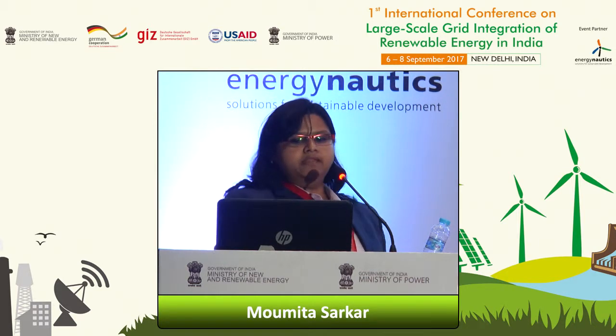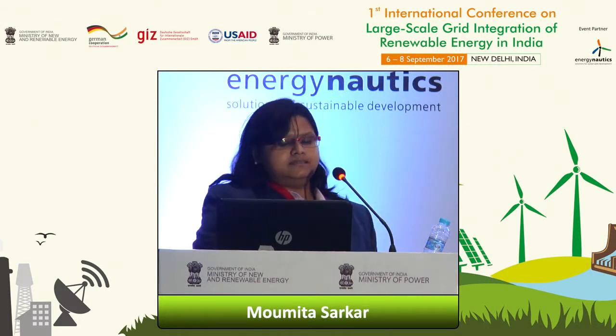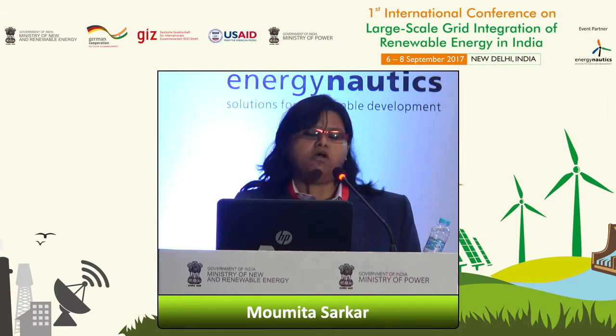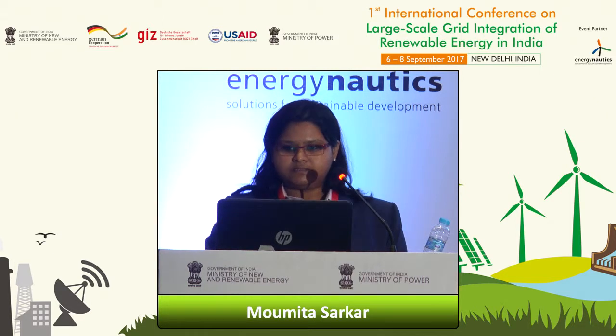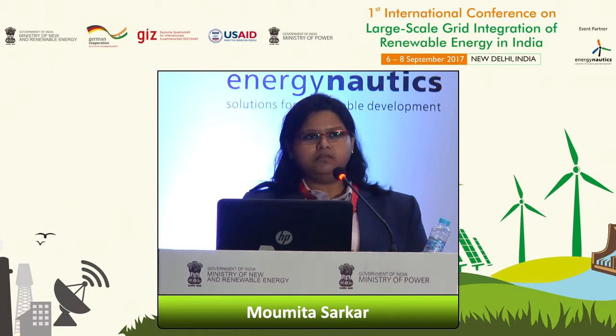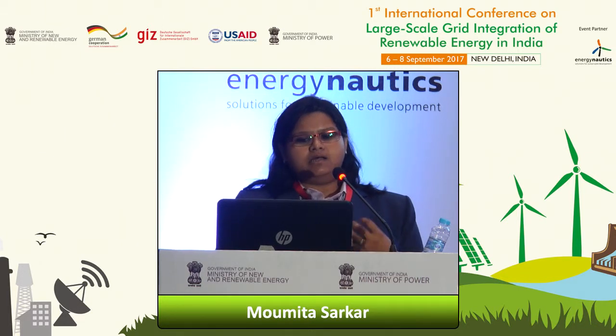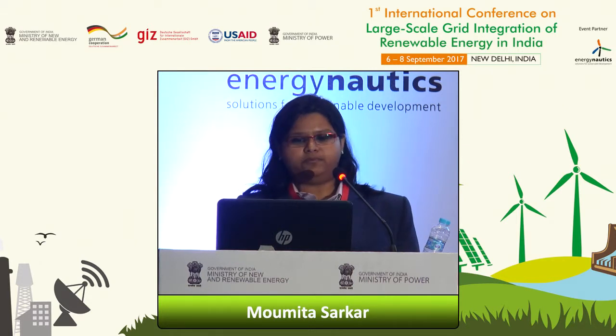Next comes the mechanical block. The mechanical block has been implemented as a two-mass model, similar to the mechanical block proposed by IEC in 61400-27-1. The parameters considered in this block are the stiffness and damping of the shaft, as well as the inertia of the rotor and the generator. This mechanical block is capable of capturing the oscillations due to sudden wind gusts or sudden changes in active power set points.